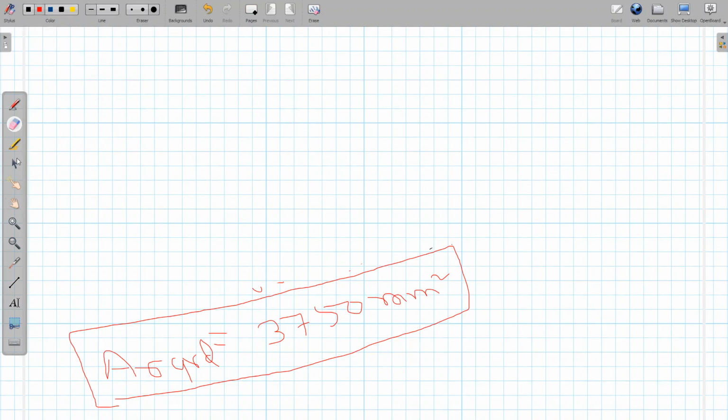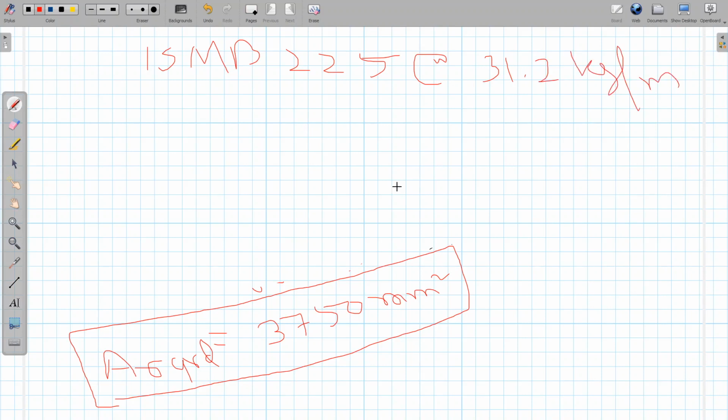So if I go to the steel table and search it, I can find a section called ISMB 225 at the rate of 31.2 kg per meter. The given area is equal to 3972 mm square. As per our requirements, this is more than 3750 mm square, so this section must satisfy.